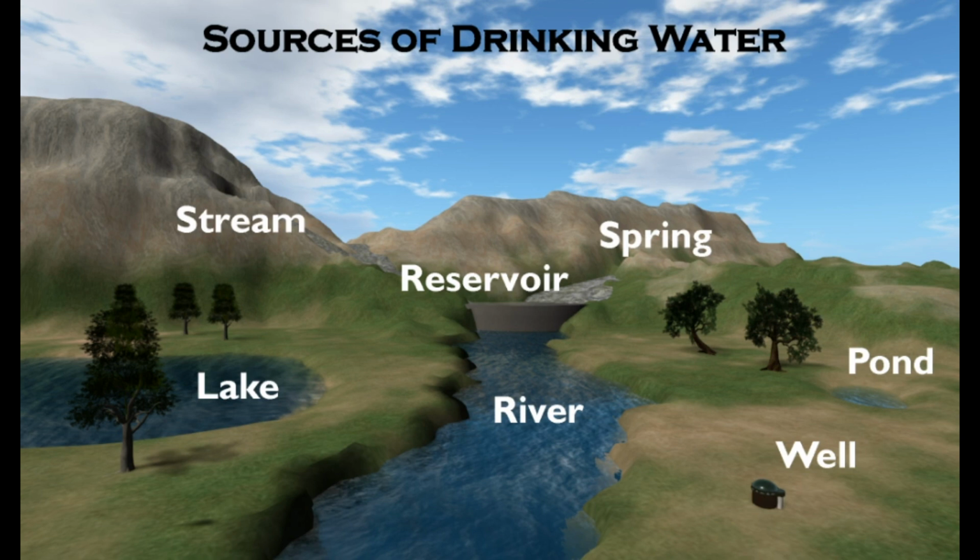Properly withdrawn groundwater will be free from turbidity and pathogenic microorganisms. It is important to select the location of groundwater supply at a safe distance from other sources of contamination. If done so, groundwater will be of high quality and can be used directly without any treatment for drinking purposes.